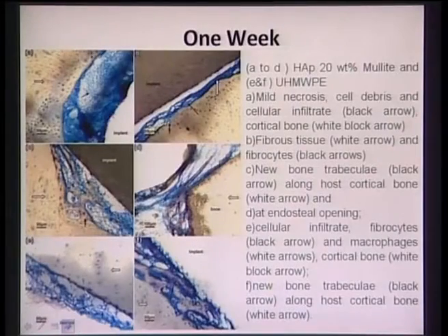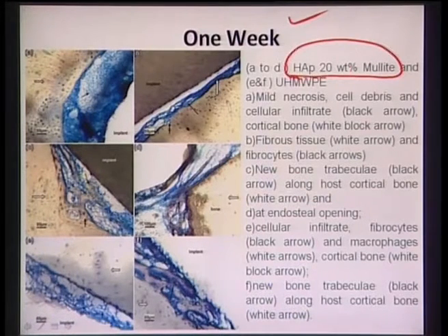Now I will show you some of the results that were obtained for these hydroxyapatite mullite composites. These tests were carried out at the Sree Chitra Tirunal Institute for Medical Sciences and Technology in Trivandrum, down south, and the test was done for short term implantation, up to 12 weeks. Now after 1 week, this is the hydroxyapatite 20% mullite. Why have we chosen this particular composition? Because this composition demonstrated a better combination of mechanical properties and a better combination of in vitro cytotoxicity, bone mineralization, etc.